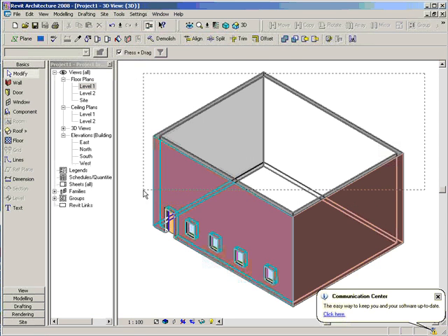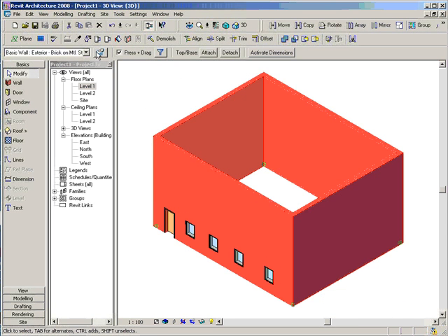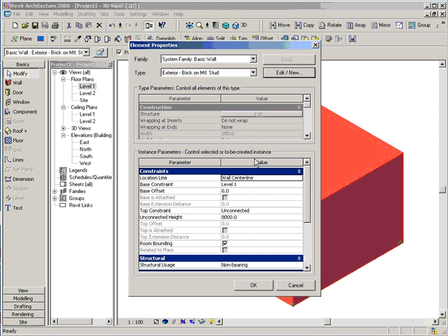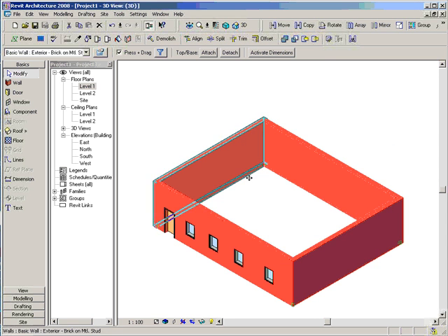Now one of the things that Revit does by default is your walls here have a certain height assigned to them. Now sometimes when you create walls in Revit, you're going to actually constrain them to levels. So let's say here you say, well, these walls, they're going to go from my ground floor or level 1 up to level 2, and they'll stop. So I'll click on OK, and that actually brings that down to wherever level 1 was.